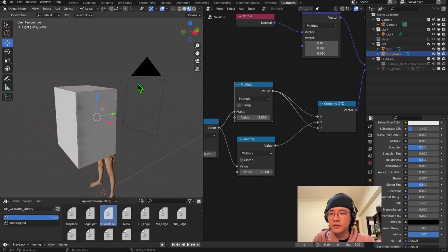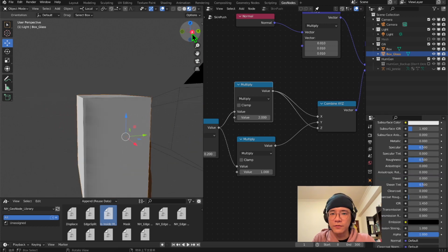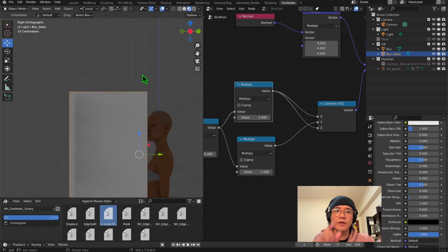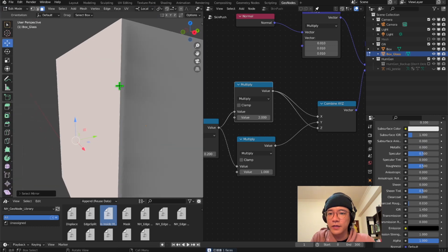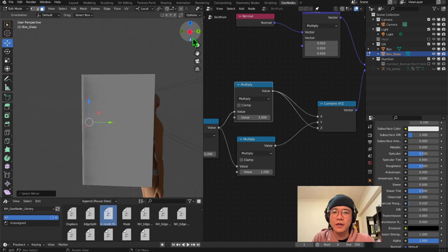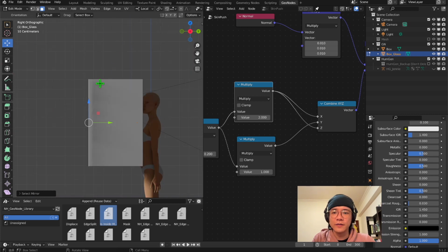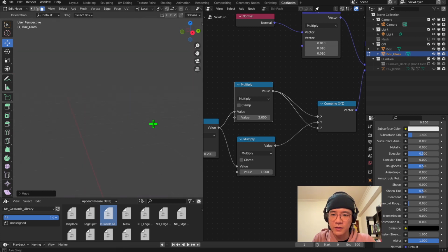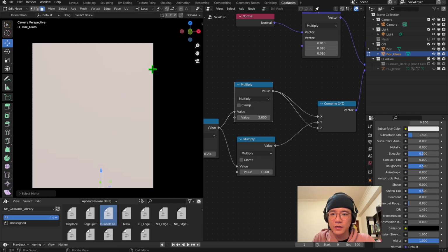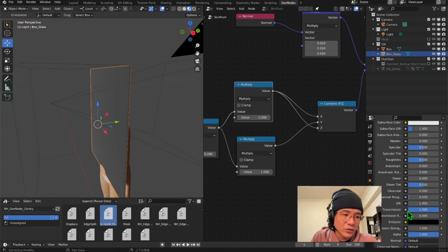And we set this material later, and we have to make it thinner. Go to the editor, take the face that is facing away, and make it how the glass would be. I think that looks okay. So just take up the translucency and the other values, just go all the way down.